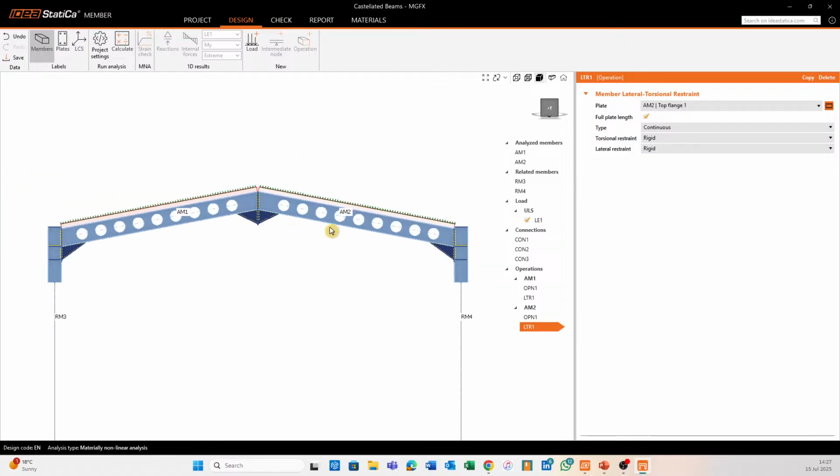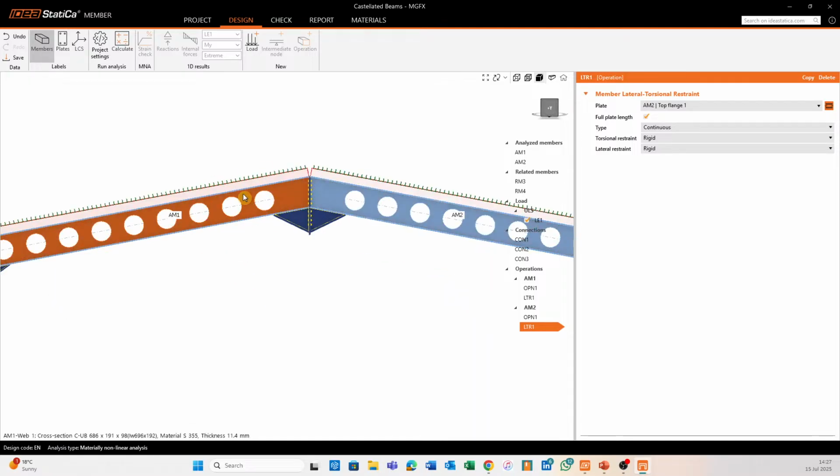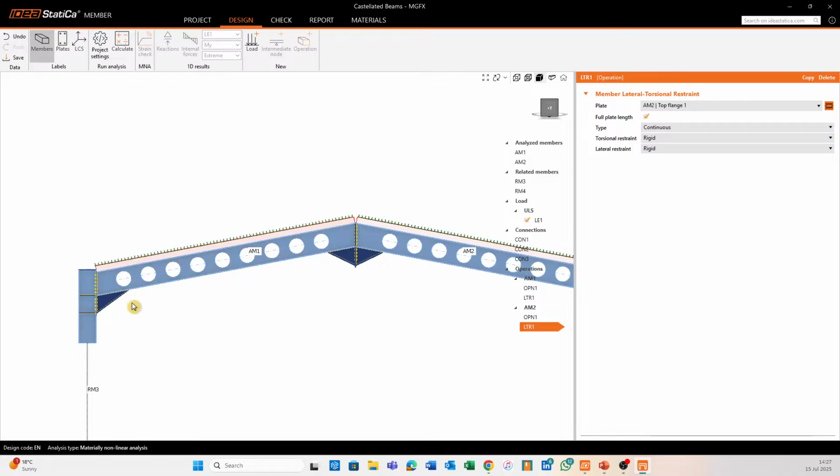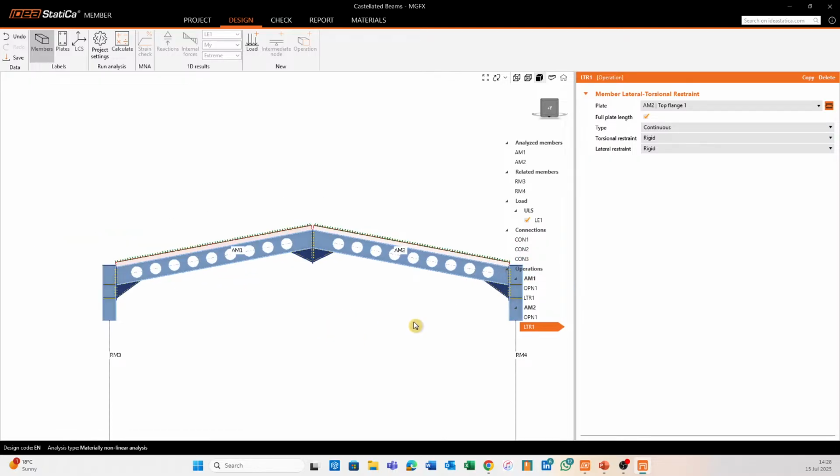Now, castellated beams, the main benefit you get out of them is just their strength to weight ratio. Even though this originates from a specific type of I-beam, with this configuration the strength to weight ratio increases quite significantly, which means that you can cross larger spans without the mass of the beam itself increasing. That means your galvanizing costs are down, and your installation costs are most likely down in some way.